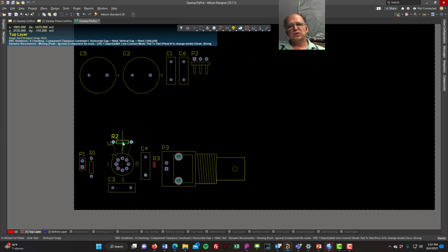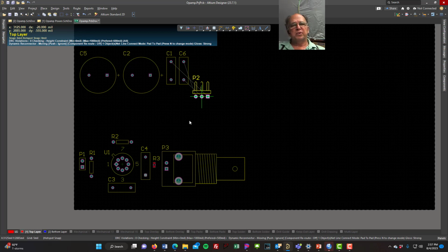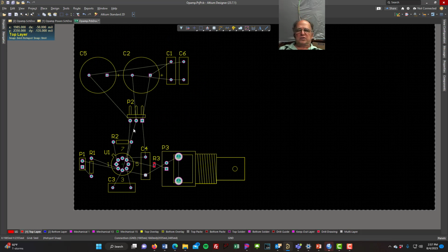Now look, if I place this close, that designator's getting eaten up by that hole, so I'm going to just grab the designator and move it. No problem. Now, if you remember, when we placed the parts, I placed the 2-pin part as just a vertical 2-pin header, but I placed the 3-pin part as horizontal. See how it's drawn on there with our top overlay? The pins come up and bend over. That way I can take a connector and push it on from the side. And the schematic parts look the same, the footprint's different, so I had an option.